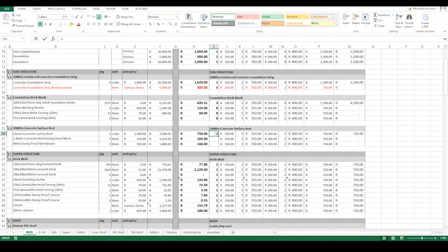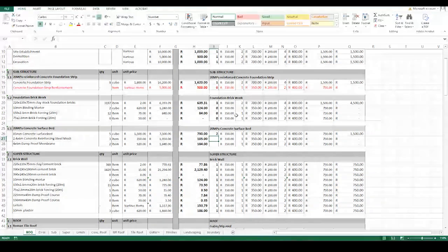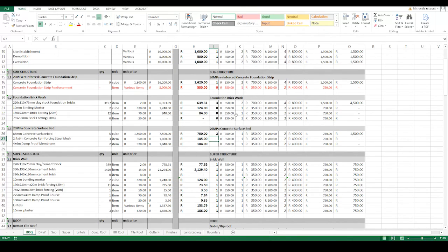So let's just say 2, because I will also need a day of reset to get the engineer on site to come and check if the work was done right. So I'll say 2 days to set up the steel work, and then invite the engineer to come in and check in the morning the next day. And then we can do a mix on site to get the actual right amount. Now the concrete foundation, so I'm going to need 2 specialists, and then 4 general laborers.